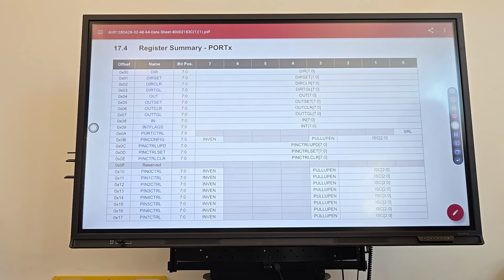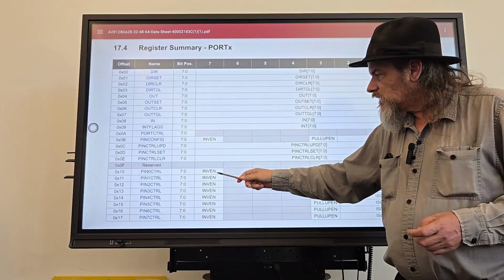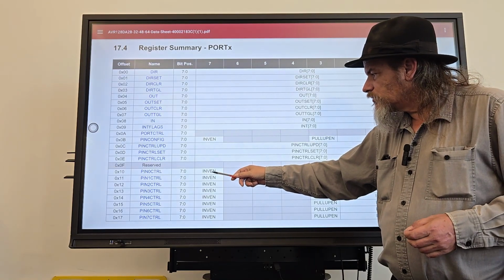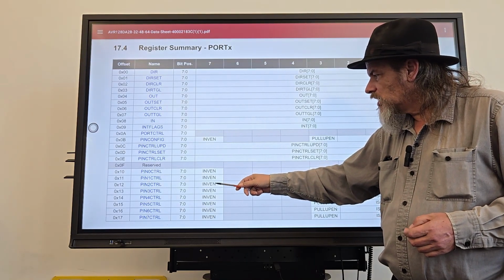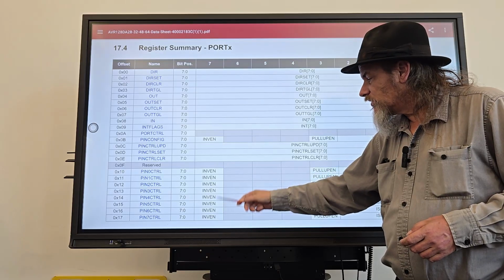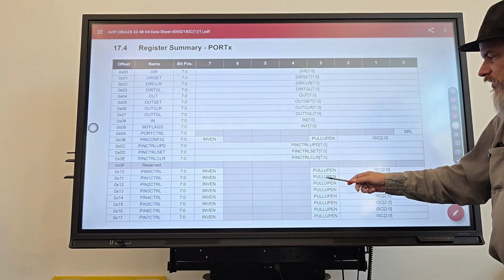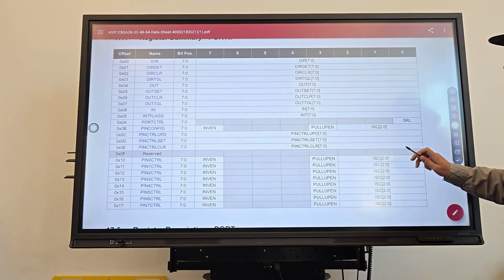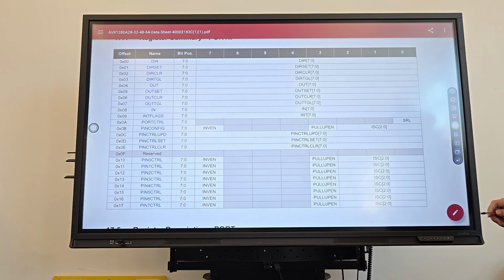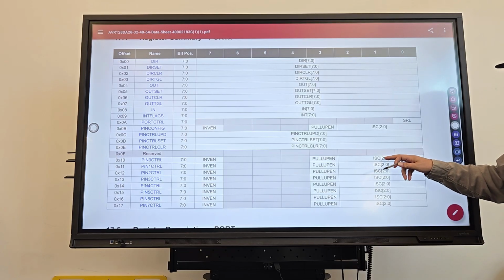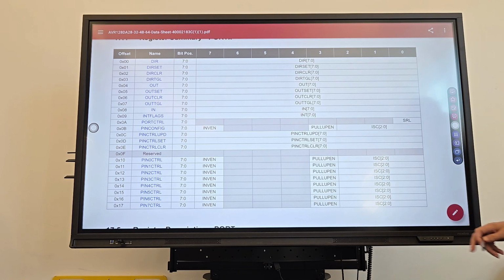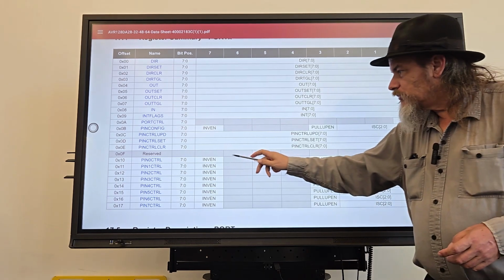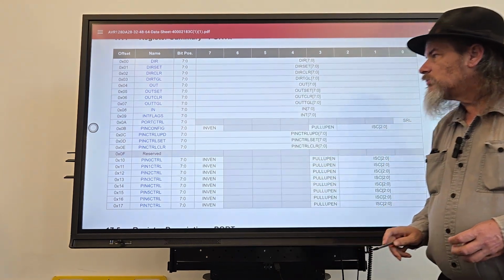You can individually control the invert enable, whether it's a pull-up resistor, which uses the internal pull-up resistor, and configure its interrupt sense control, for each individual pin of the port.